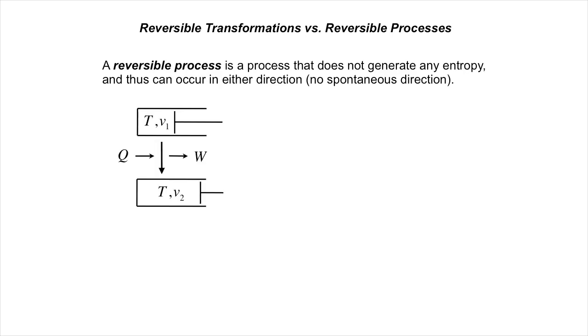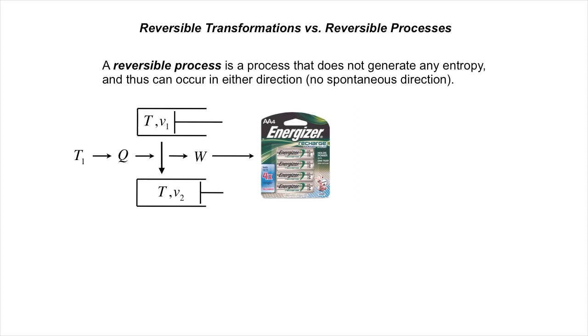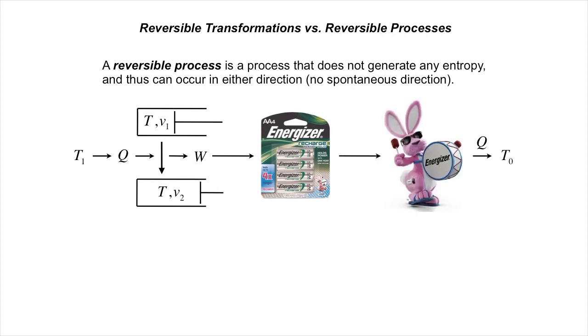For example, imagine that we measure the change in entropy of a non-ideal fluid via heat flow during an isothermal expansion. We do so very slowly, such that the fluid is maintained in a constant state of equilibrium during the entire transformation. However, to get the heat into the fluid, we need to transfer that heat from a heat source. This involves gradients in temperature outside our system, so generates some entropy there. Also, imagine that the work we do during the expansion is stored in a perfectly reversible set of rechargeable storage batteries. But a month later, we discharge these batteries in a device, generating heat which ends up in the environment.